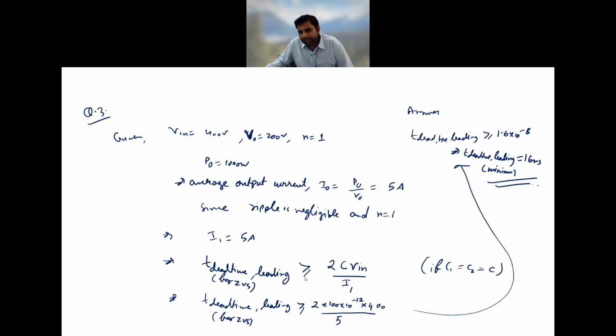And if you don't put the dead time equal to this, then you will not achieve the zero voltage. The voltage across the switch will not come down to zero. It may be less than V in, but it is not equal to zero. That particular condition is called the quasi short switching case, or quasi ZVS condition, or sometimes also called valley switching.